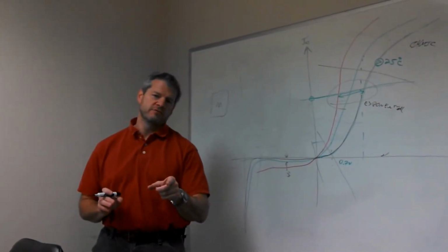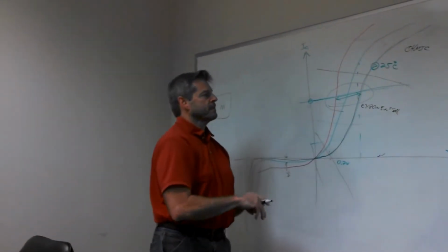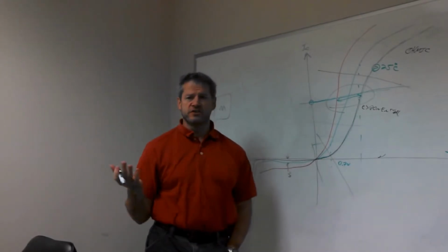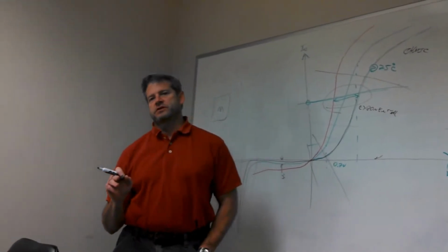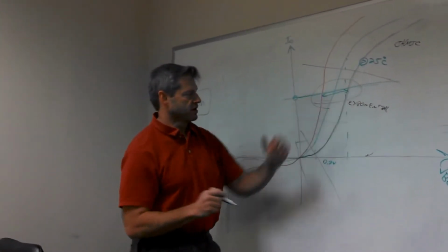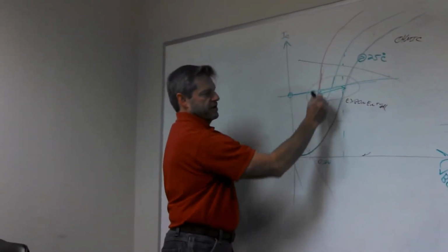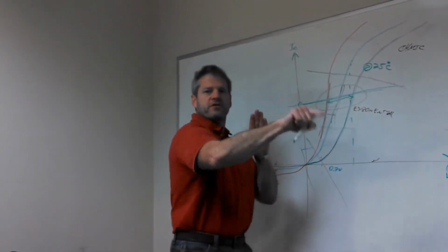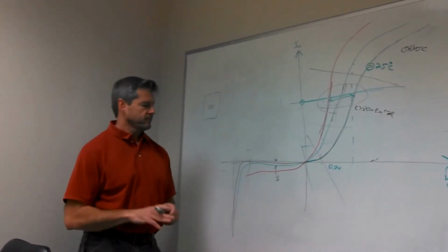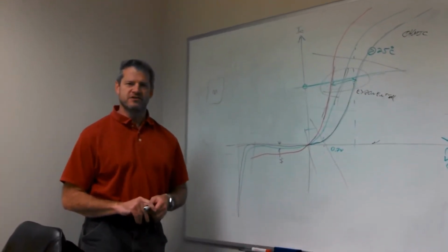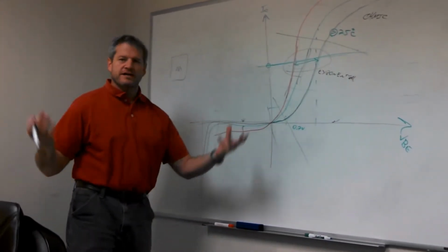With digital logic, it's not a big deal because we're just using the switches. We're banging them in and out. We're way over here somewhere and way over here somewhere, so the change is going to be very little. Going to the analog world, where I'm used to working, it can make a big difference in how your circuit operates. Because now you're shifting these curves, and what you're normally doing is running up and down these curves. My curve moved from here over to here, and that's affecting something further down the line. And it becomes important. I have seen that rear its ugly head and cause things not to work on some projects before. And then you get into the whole idea of corner testing.